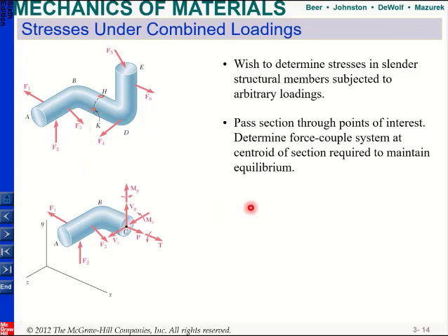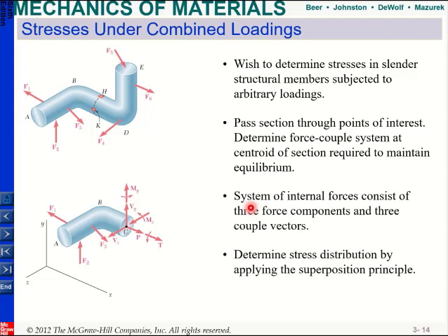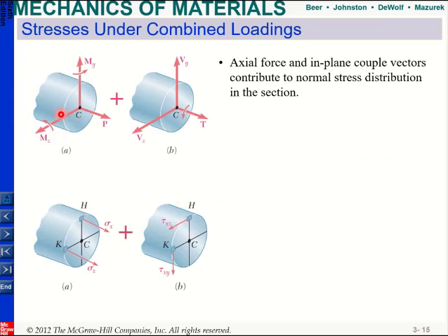But when you do that, you will end up with three forces. For example, in this case, you will have Fx, Fy, and Fz, and you will also have Mx, My, and Mz. So you will have three forces, and you will have three moments. And it's important to identify which forces create what kind of stresses. Okay, so this is why when we group them, we will group like this.